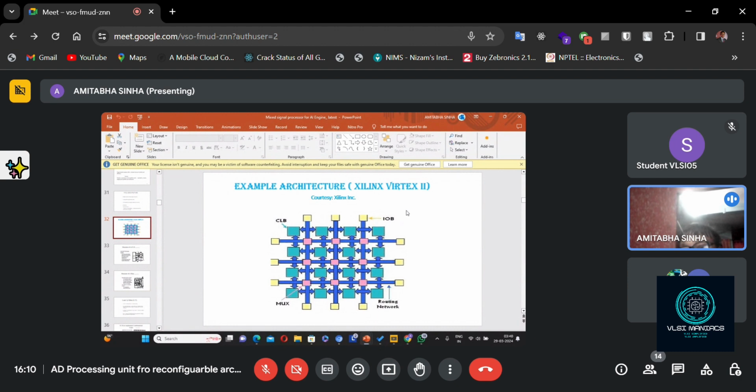And as the complexity of the circuit increases, the complexity of this router will also increase. Power dissipation will also be more. And to reduce that power dissipation to a certain extent, some intelligent power dissipation circuit has to be given. So that is an additional circuit. That's why the cost of FPGAs is much more than ASIC. But ASIC doesn't offer the flexibility. So this point has to be made very clear.